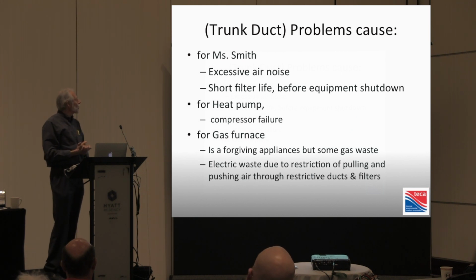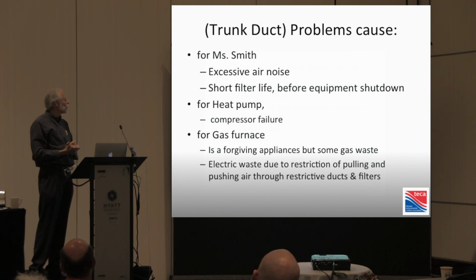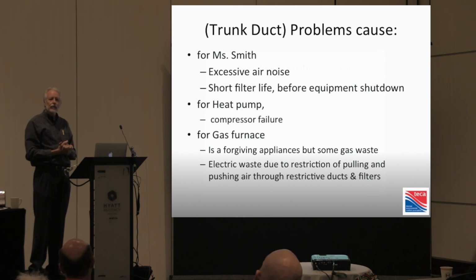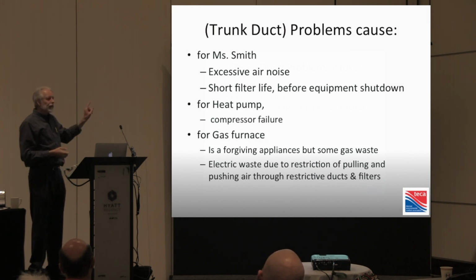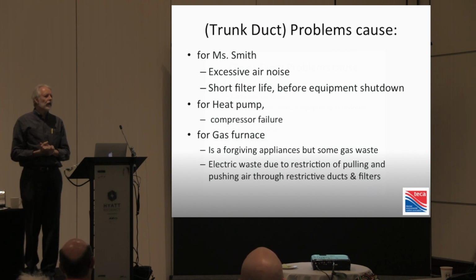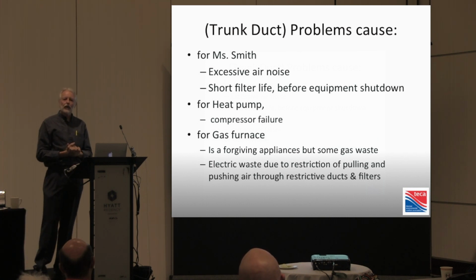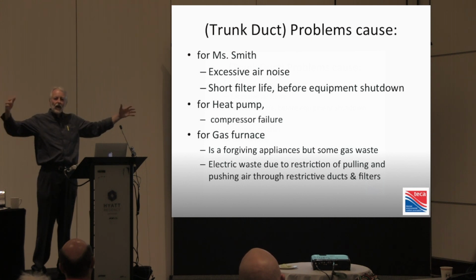What is the problem the trunk ducts cause? If they're undersized or badly designed, you get equipment and excessive air noise. And I'm sure lots of you have heard of air noise problems. The sleeper, however, is filter life. Every piece of equipment on the market today has what's called a sweet spot. It's a sweet spot where it moves the right amount of air to take the heat or cold off the appliance.